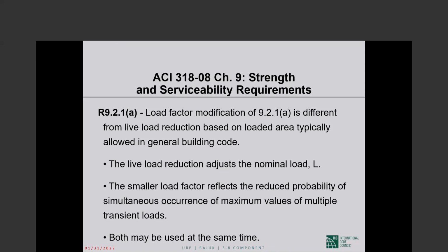So the live load reduction accounts for the fact that if you have a large area, it is extremely unlikely that the entire area shall be subject to the full design live loads. The larger the area you are talking about, the less likely it becomes that the entire area will experience the full design live loads. So that's live load reduction.